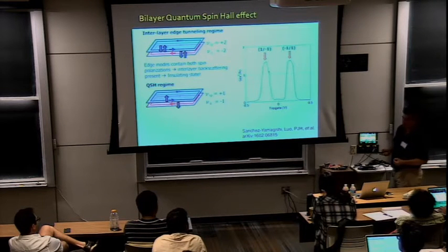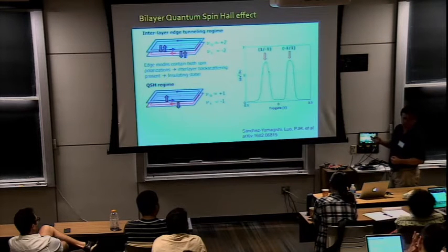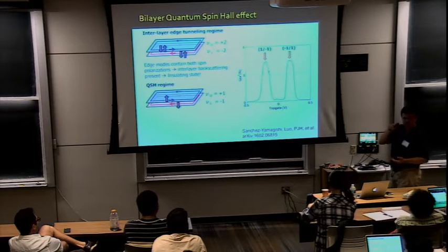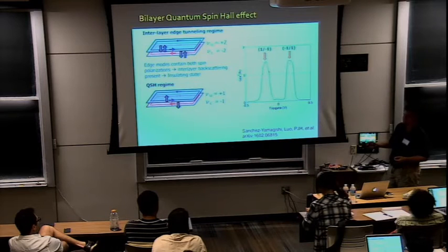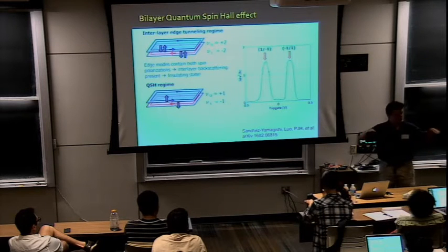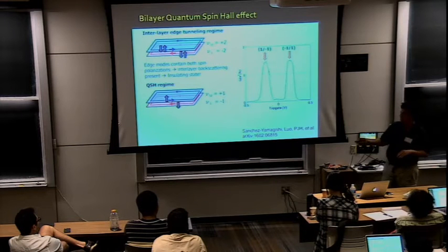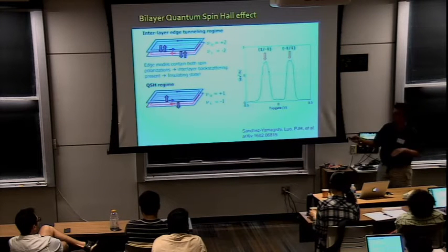Okay, so we think the primary reason why it's not 2e²/h is not actually some intrinsic backscattering, but it's this effect that I mentioned before, that because we have one layer p-type and the other layer n-type, your metal contacts tend to dope the graphene either p-type or n-type, which means one of the two layers always exhibits a p-n junction, which has an enhanced resistance with respect to the metal, and that decreases the value of that conductance.